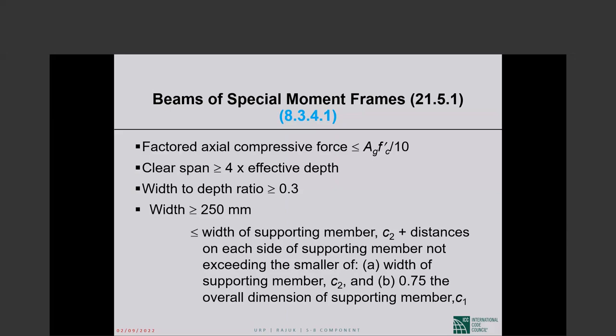If you're talking about existing buildings, I do not know. That will have to be case by case. If you're talking about a new building, it is very, very simple. You have to figure out the actual height of the column in service. It is the actual clear height of the column that will govern the shear that develops in the column.